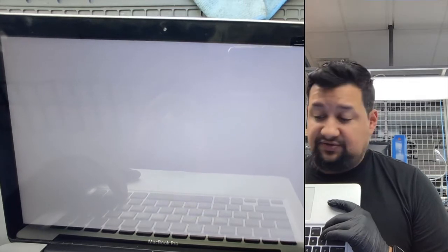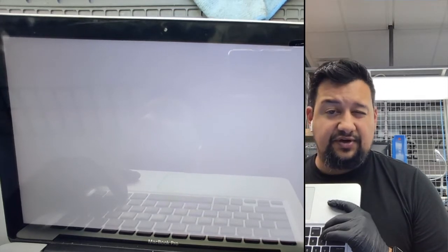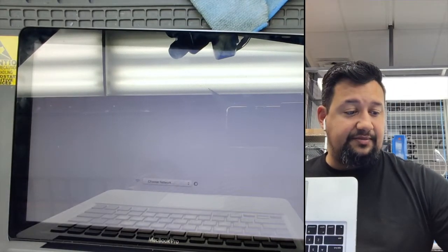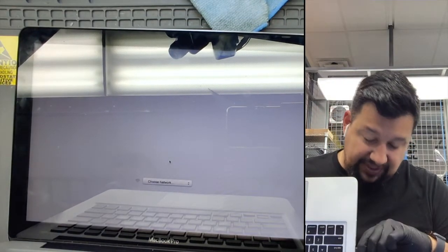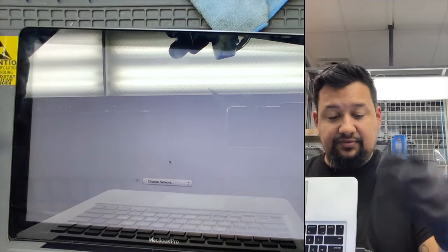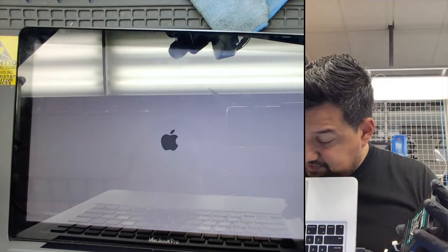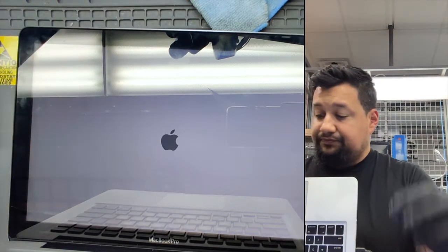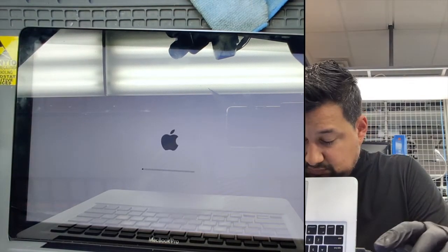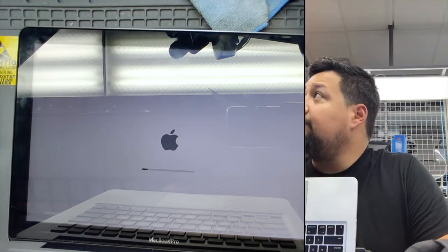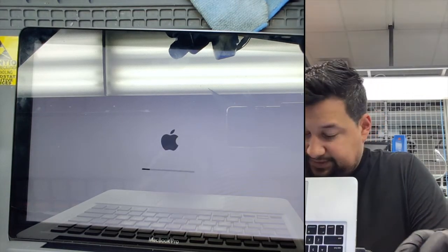I was checking my fan with the SMC fan control software, and it was reading 0 RPMs. So it wasn't detecting the fan movement. So let's be sure that that's not happening anymore. And if that's the issue, we're good. We have the MacBook done, and that will be all for today.